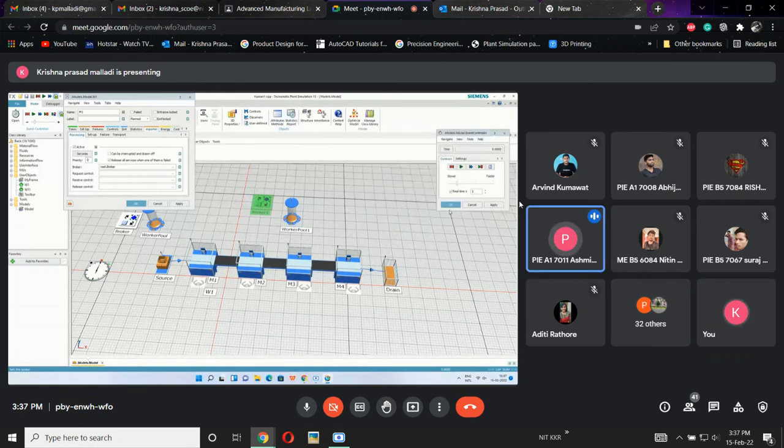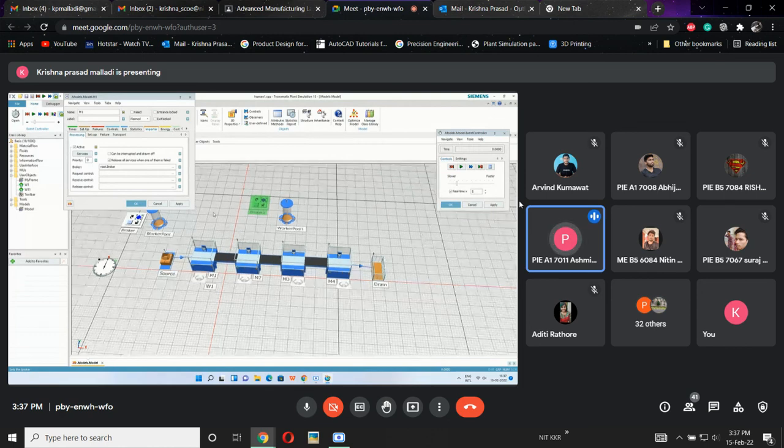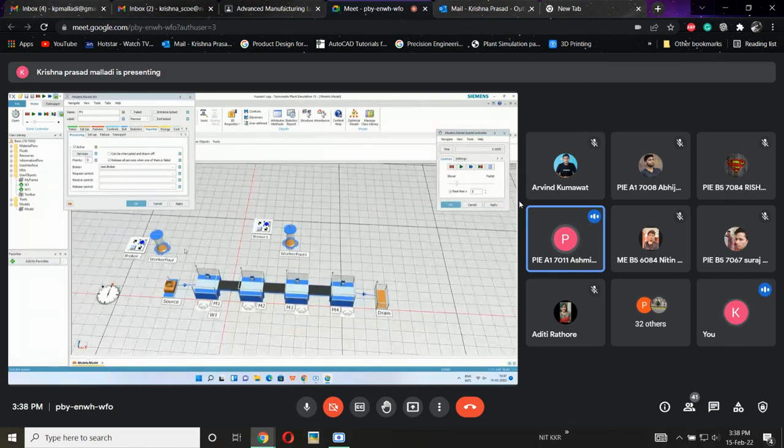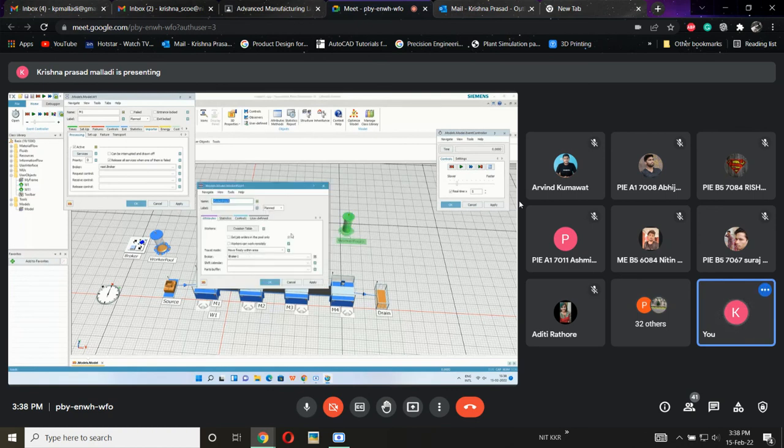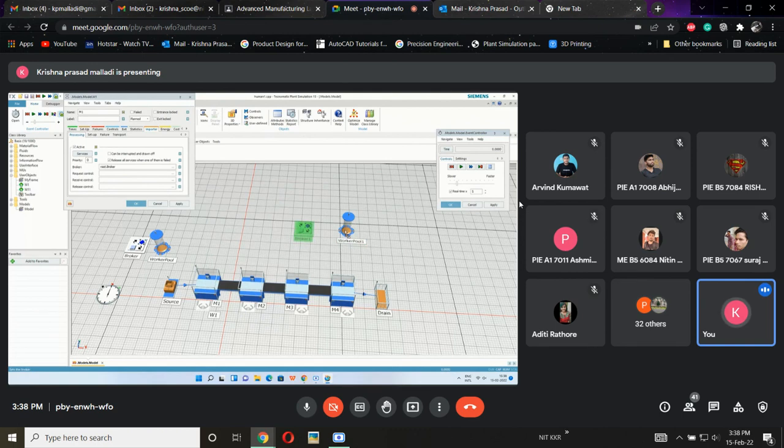Okay, sir. So this means that the work pool and broker connect to each other automatically when we click the work pool first and then the broker icon? One, you need to verify that. See, you can pick the work pool first and the broker second. There are no default options. Once you have assigned them, you need to drag and drop, which means you need to assign it. Then they will have a relationship with each other. If you don't assign it like this, then this work pool will have a relationship with this broker by default. That also has a problem. Okay, sir. Fine.